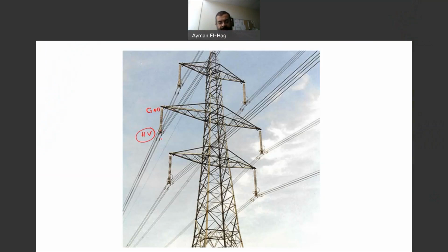So, okay, we understand that this area will have very high electrical stress, and we have to use a corona ring to reduce the electric field. But why sometimes do we even find erosion in this area, at the grounded end, where the voltage is zero? So how come, at the region where the voltage is equal to zero, we have some erosion in the outdoor insulators? And here specifically we are talking about polymeric insulators.